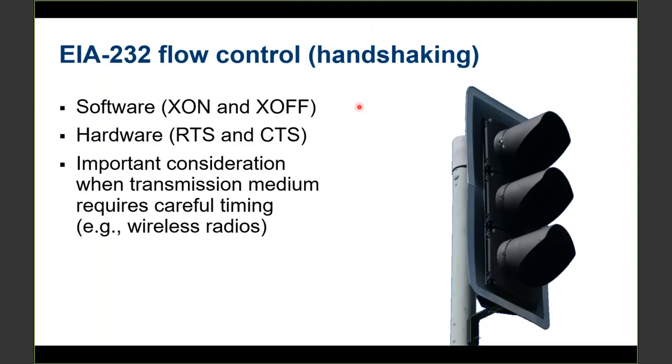So basically, if one device needs to transmit onto the comm network, it will assert its RTS pin, the request to send. So it's asking the remote end if it can send data over the line. The other end will receive that on the CTS pin, and it will grant permission by asserting its RTS pin, which is wired to the local CTS pin.